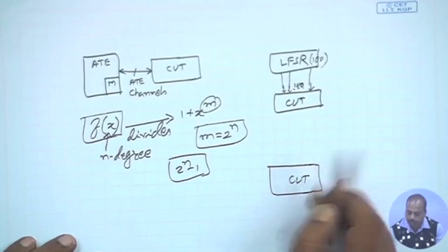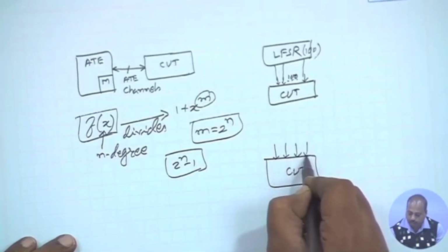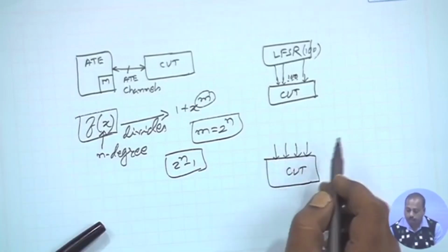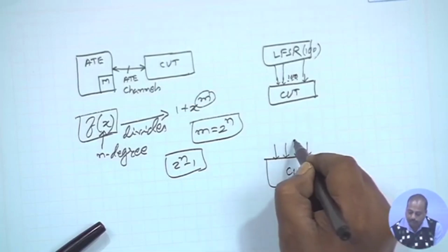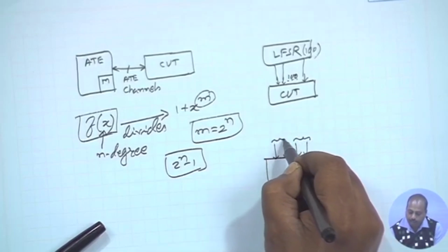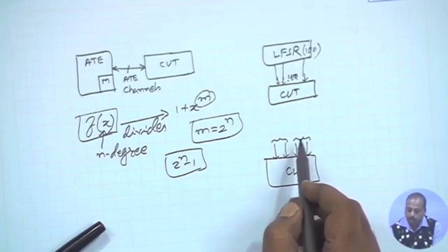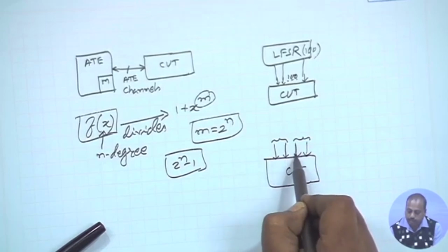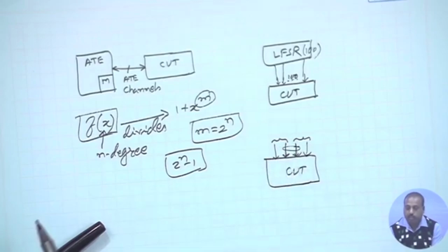in exhaustive testing, if it has got these inputs, we would generate exhaustive patterns for all the 4 inputs. But it may be sufficient that I generate exhaustive patterns for these 2, and exhaustive patterns for these 2. For the remaining ones, I do not. So, the patterns that I apply are not exhaustive when we consider, say, these 2 inputs.